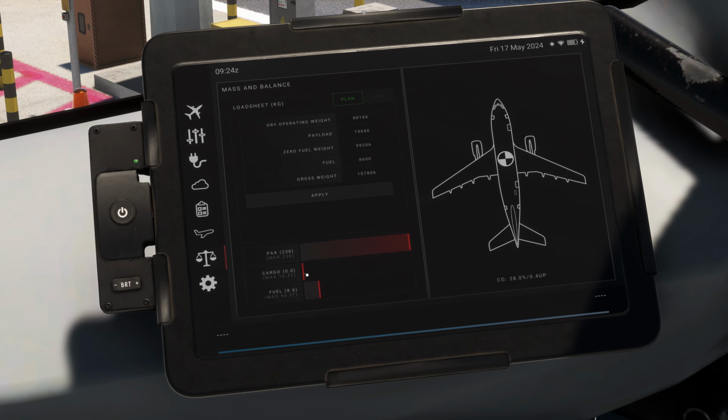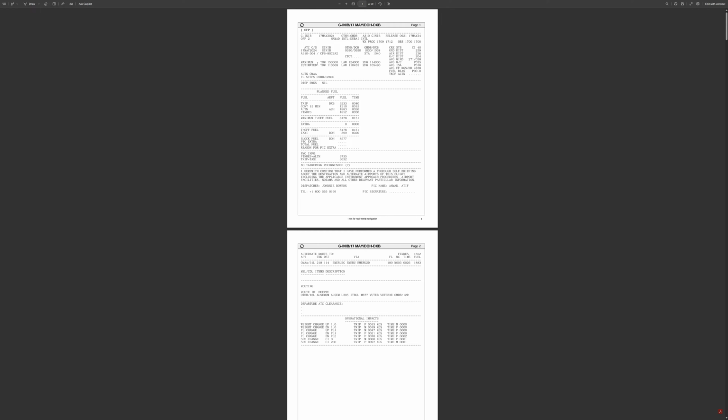Now you have to set the cargo. It's a tricky thing. And there are two things that you can do: either match the gross weight or the zero fuel weight with the weight given in the operational flight plan. So if you look at this part of the operational flight plan, it has got two readings coming. One is the maximum, another one is the estimated. Maximum is the maximum that this plane can carry, and estimated is as per the operational flight plan that we have made. This is the takeoff weight, 113,000 kilograms or 113 tons.